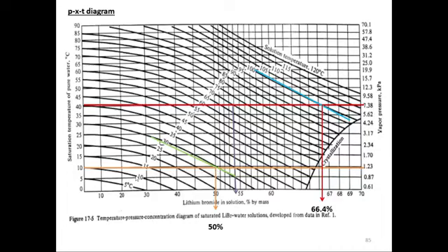So the same diagram, this is a cutout from the 17-5 and this is the whole 17-5. I have drawn an evaporator line which is at 10 degrees centigrade. This brown line is the evaporator line, 10 degrees centigrade, temperature on the left hand side, and the corresponding vapor pressure is 1.23. Similarly, the condenser is at 40 degrees centigrade and the saturation pressure of water at 40 degrees is 7.38. So these two lines show the temperatures of the evaporator and condenser. The solution in the generator is 100 degrees centigrade, so wherever it crosses our 7.38 pressure line, that's the state of concentration in the generator. If I draw the vertical line from here, I can read the value of the lithium bromide in the solution, which I am saying is 66.4%.